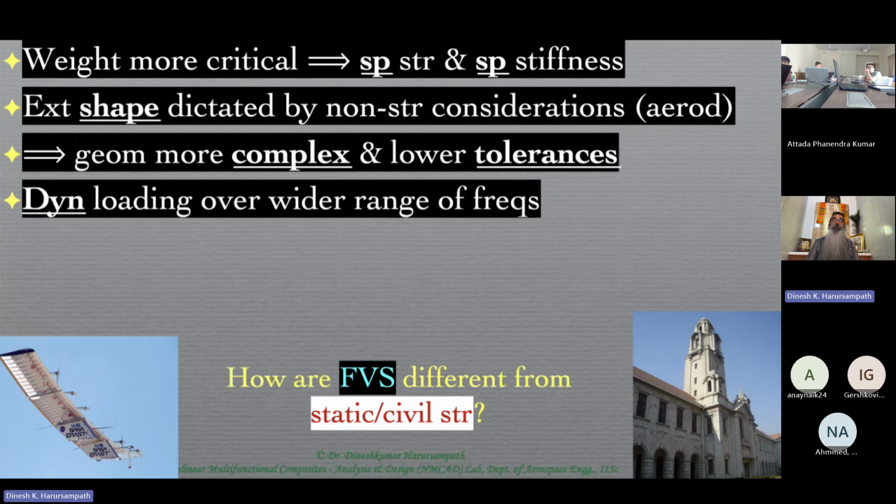The primary aspects come from the sizing of the building in terms of what it is supposed to be for, the primary functionalities, how many people it's going to house, what kind of infrastructure it's going to house, apart from the building's self weight, and what kinds of equipment are going to go into that building, etc. Those are the things which predominantly determine the loading. Most of which are static loads. Very few of them are dynamic, and the frequencies at which they occur are almost precisely known, in very narrow ranges compared to this.